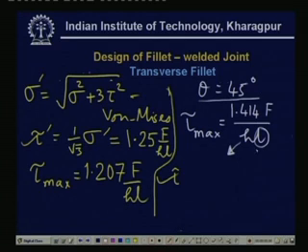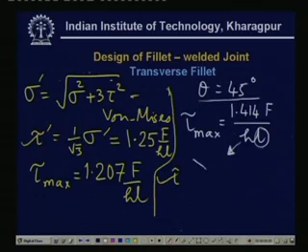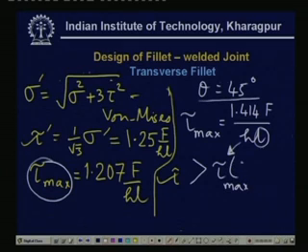the normal force on that particular section, then we get tau max equal to this value, and this is of course greater than the tau max obtained here from the strength of material approach. Or maybe it is greater than even tau prime, which is the corresponding shear stress in the von Mises failure criteria. So, this is a very conservative result which we have for this transverse fillet.